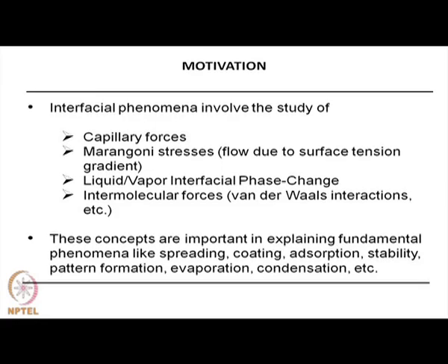We are also interested to know the liquid vapor interfacial phase change. What happens when a thin liquid film separates a solid from the vapor, and how much evaporation we may get from this liquid vapor interface is going to decide the heat transfer process, and we will see how from the ultra thin part of a thin film there can be very high heat and mass flux.